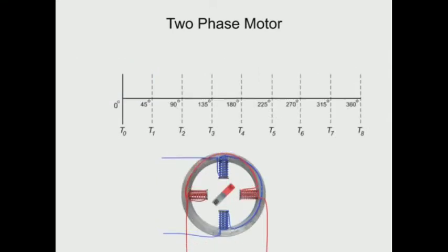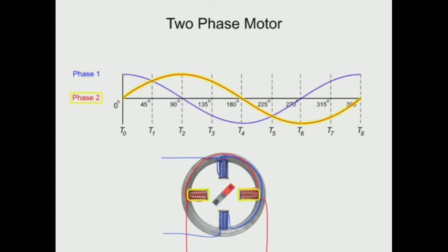fixed magnetic field. Synchronous motors can be operated using single-phase AC, but such units are used for only very low power, 0.1 horsepower, and suffer from very low starting torque. When operated from three-phase AC, synchronous motors can be operated at very high power, up to 50,000 horsepower.